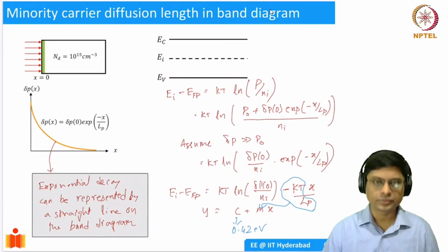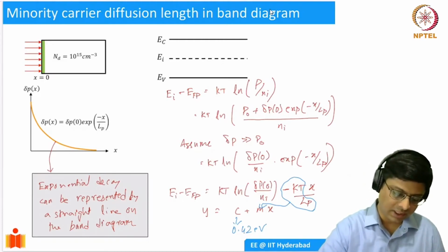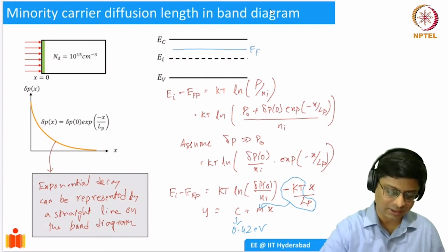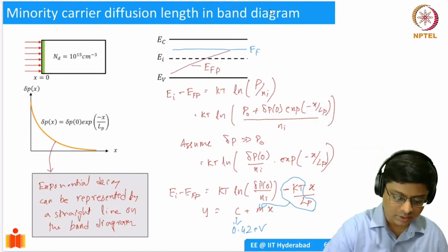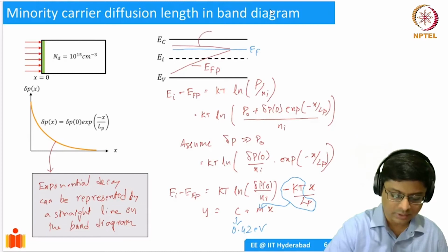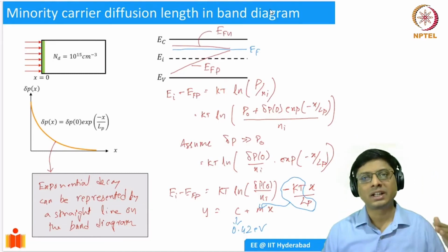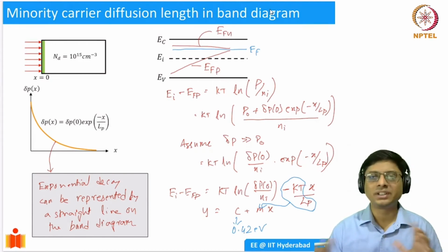All right. So what I'll do is I'll pick up my EI when we have done it in the last slide. So essentially this is going to be your EFP. And this is EFP. You see, the quasi Fermi level for the electron is not really moving that much because it's a majority carrier, and we saw that the total density doesn't move so much, right?